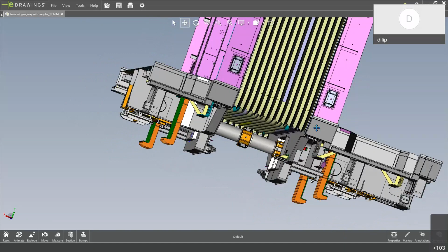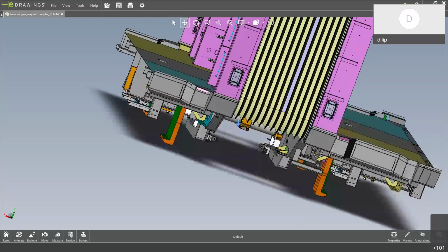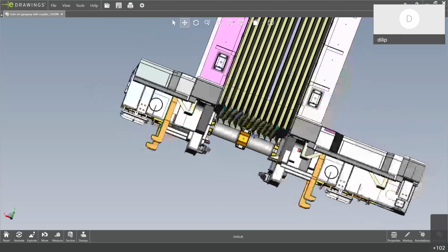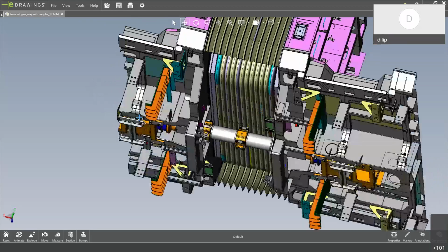If any configuration has to be changed, a lot of electrical cables have to be disconnected, and a lot of other work is needed. So this will happen only in the depots. Here we wanted to give the passenger the flexibility that he can move from one end of the train to the other end without any hindrance. To facilitate this, the coupler has been lowered from the regular 1105 mm to 940 mm.